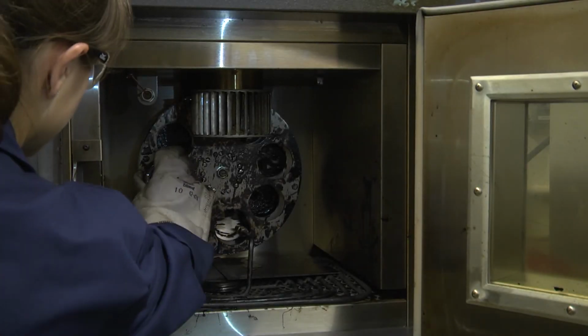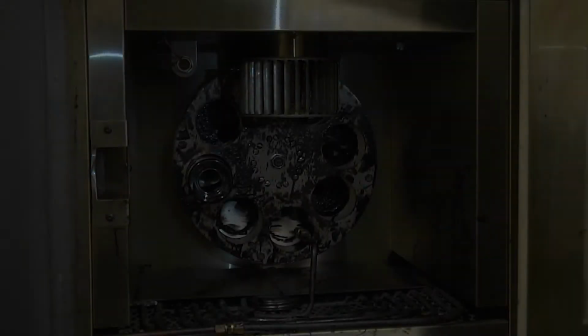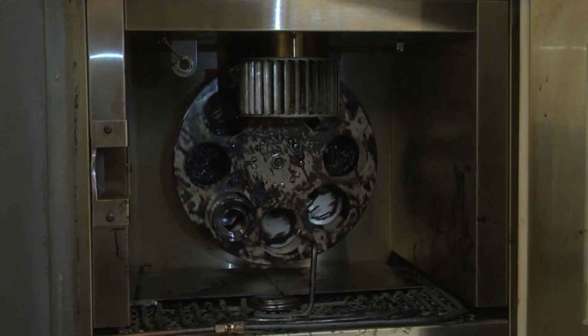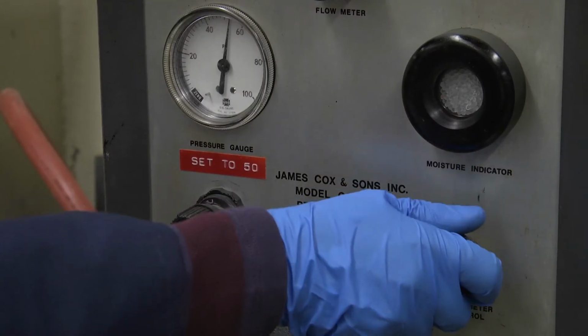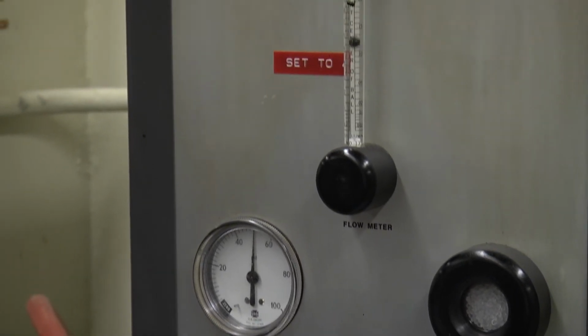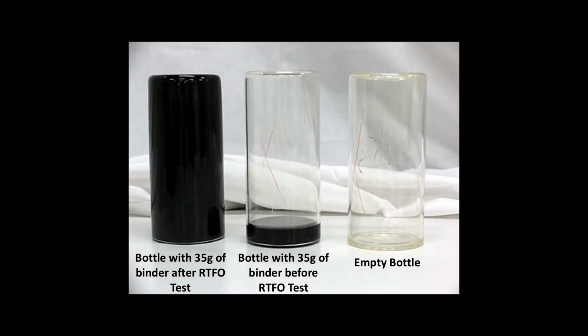Place the bottles in the preheated RTFO oven carousel and close the door to prevent heat loss. Then, start rotation of the carousel at a rate of 15 revolutions per minute. Set the airflow rate to 4,000 milliliters per minute and set a timer for 85 minutes. Upon rotation, the asphalt binder will be dispersed as a thin coating on the inside of the glass bottle, which increases exposure of the binder to heat and airflow, expediting the short-term aging process.